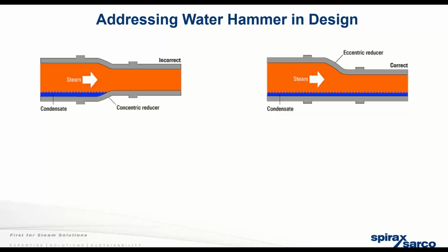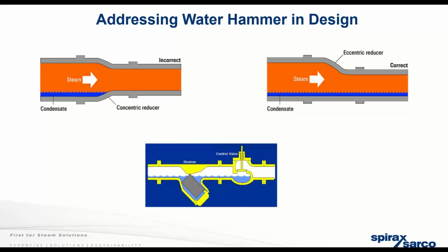I'll just go through this here quickly. So back to, I just want to introduce a couple basics of our steam supply system. We do not want water in our steam systems. That's the idea. Water is a consequence of saturated steam. So we want to pipe it properly. Don't want to use concentric reducers. We just want the steam to flow and the water to be separate from the steam and not create those waves in slug flow transients.